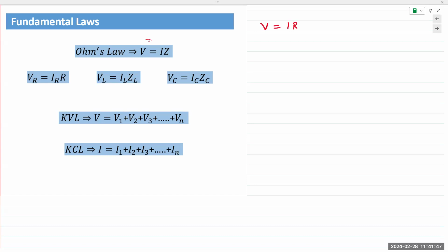You perform complex math, you can replace I with Z and it becomes V equals IZ. If you use RMS values and not peak values, and we don't need the phase, then we can also use V equals I times X. It works exactly the same. So instead of doing V equals L di over dt, or the capacitor current IC equals C dV over dt, doing differentiation or integration or solving differential equations, we simply perform multiplication.